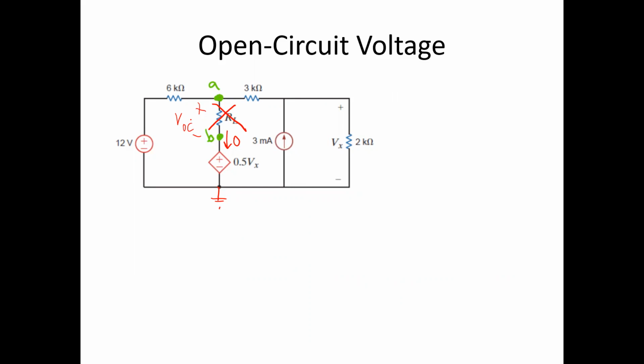Okay, so there's a number of different ways that you could have gone about doing this. One way of dealing with it is to just cycle through and ask yourself, how many equations does it take to solve? If you look at this circuit, we have only one other node here. Let's call this node C. And one of them is ground. B here is not really playing a role in the node voltage method. So we essentially have two node voltages that we need to solve for.